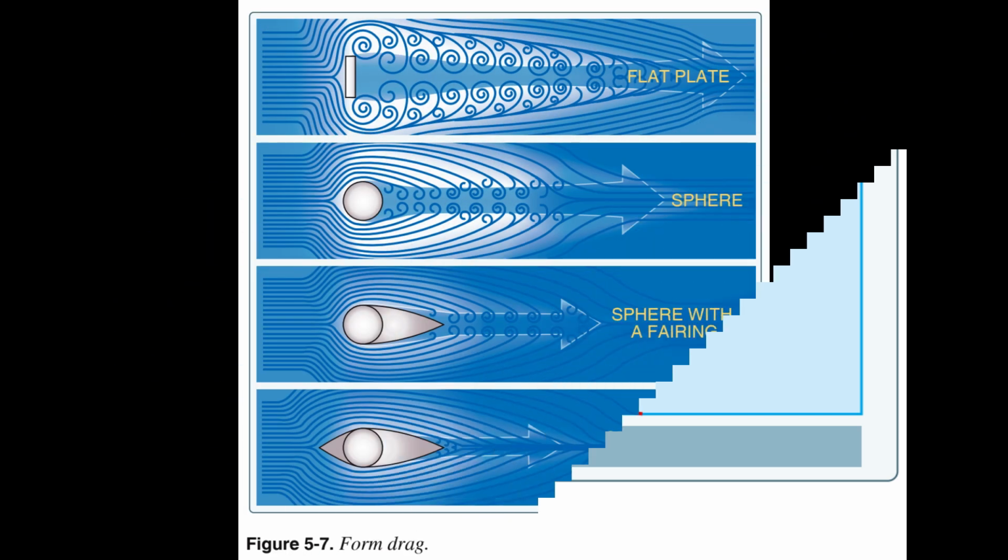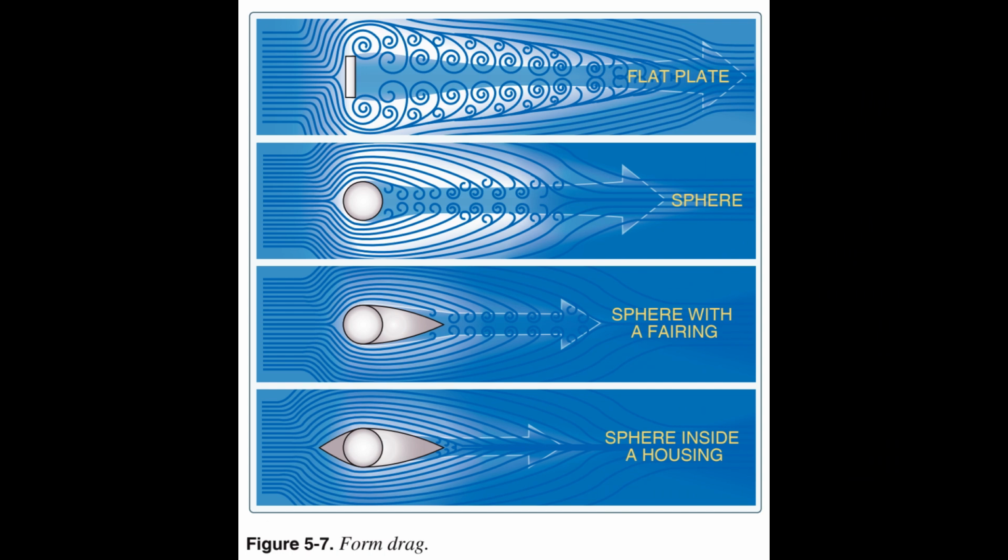Form drag. Form drag is the portion of parasite drag generated by the aircraft due to its shape and airflow around it. Examples include the engine cowlings, antennas, and the aerodynamic shape of other components. When the air has to separate to move around a moving aircraft and its components, it eventually rejoins after passing the body. How quickly and smoothly it rejoins is representative of the resistance that it creates, which requires additional force to overcome. Figure 5.7.